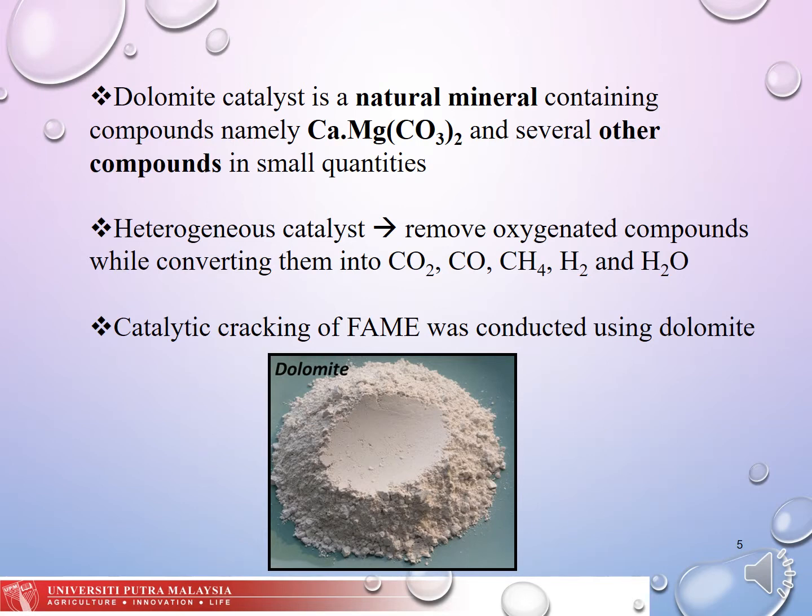Why do we choose dolomite as catalyst? Because it is a natural mineral containing compounds mainly like calcium, magnesium, bicarbonates and several other compounds. Besides, it is also a heterogeneous catalyst which can remove oxygenated compounds while converting them into carbon dioxide, carbon monoxide, methane, hydrogen and also water.